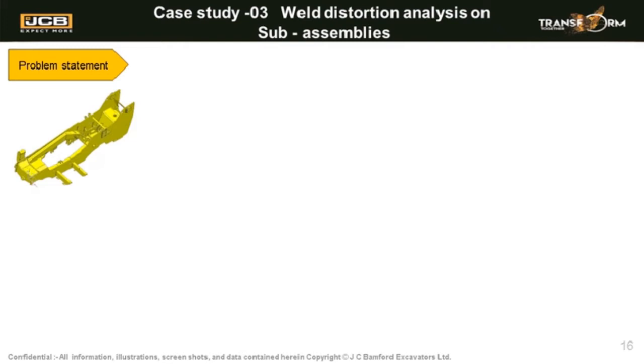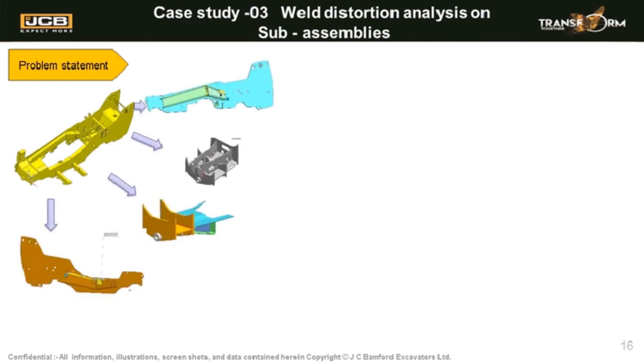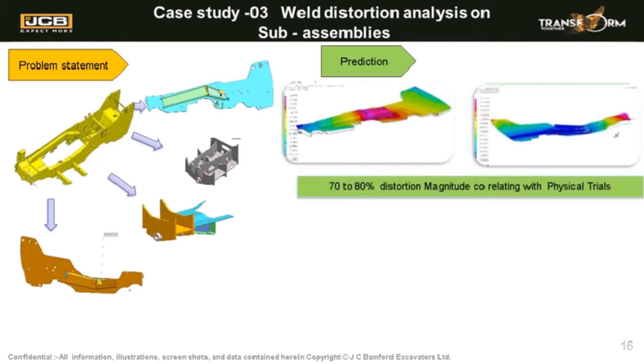This case study is where we've got a very large chassis, and right from day one it's always been welded in a single fixture. However, there was a proposal to make it into 4 main sub-assemblies and then bring it into a final welding fixture, and that really gave us a lot of operational flexibility. But before committing to the expense of tooling trials, simulation was done to optimize those weld sequences and reduce distortion, and to build the business case before investing any physical resources.